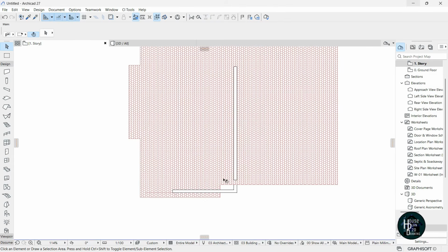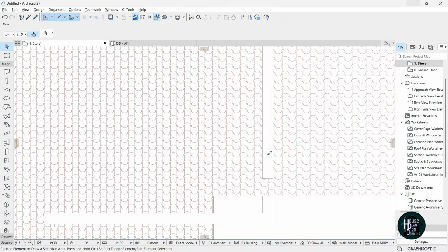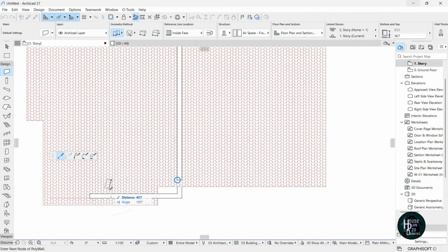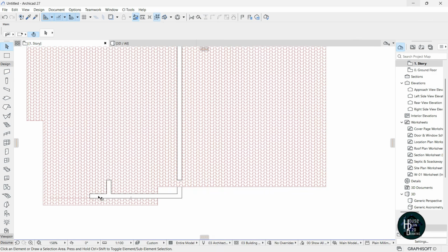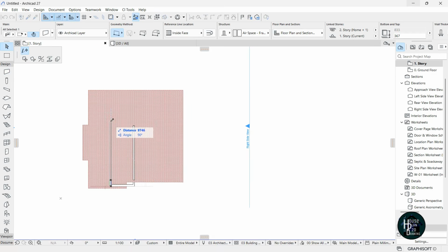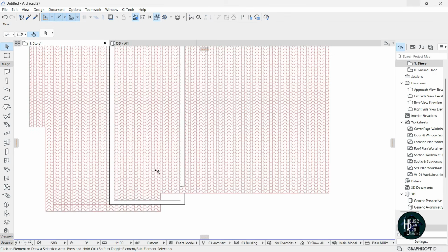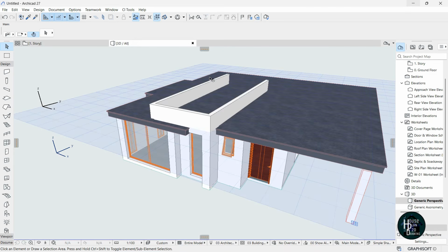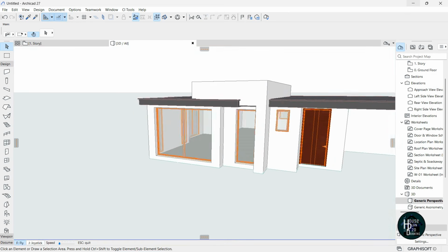Okay, so I'm just going to hold on alt, select this, put the cursor here, allow it to load up. Now I'm going to give it a distance of 3350. Click enter, and I'm just going to stretch this like this. Double click, hold down control, cut out this side, click this and click on this and stretch it downwards like that. So remember that I'm actually designing for the first, sorry, on the roof rather. So if you go to a 3D model, you should have that being corrected by itself. Okay, so just please bear that in mind.